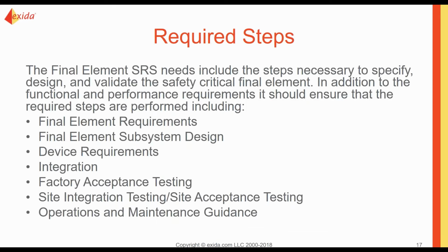So we're proposing that a final element SRS should be created and should not only include the requirements, but should ensure that the steps necessary to design and integrate that final element are included. So if we look at that, let's think about what they would be. We need final element requirements. We need to do an evaluation of that subsystem design. From there, we'll flow those things down to device requirements.